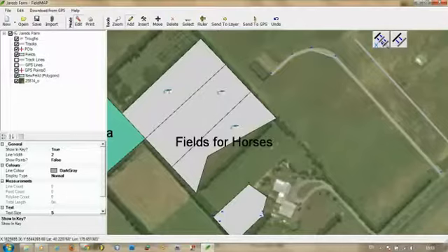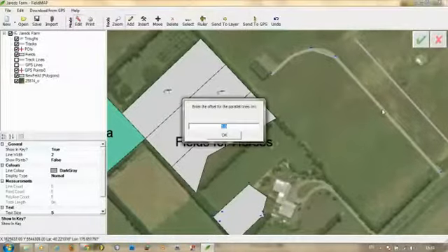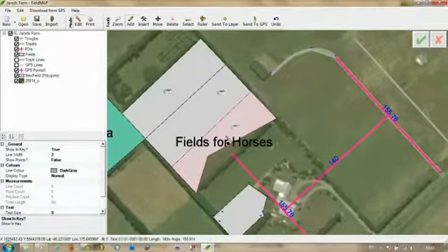The Fixed Interval Multiple Parallel Line button lets you set a fixed interval, or multiples of, between parallel lines and place them. Select a button. Then click on the line that you wish to replicate and drag the mouse out to where you would like the new line to sit. If you have chosen a fixed interval, it will prompt you to enter the interval size. After you specify a value, click OK and it will snap to that interval from the original line.